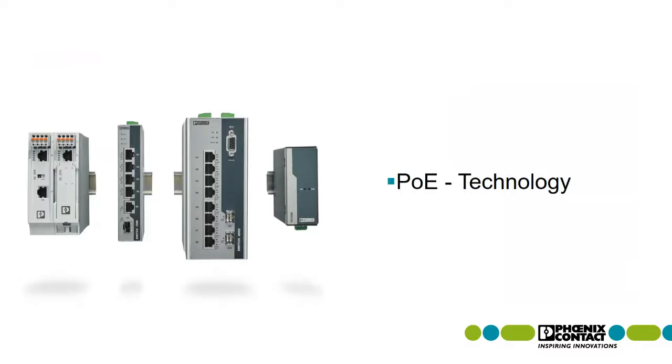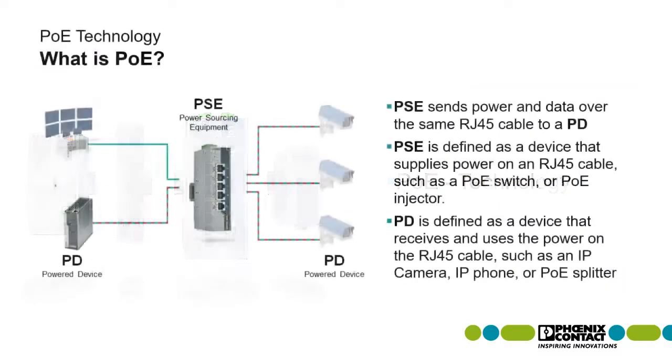So first, taking a brief look at PoE technology. PoE is made up of different device classifications. Mainly, you've got a PSE, or power sourcing equipment, and then you've got PDs, or powered devices. The power sourcing equipment is responsible for sending that power and data to the end device. It's all done over the RJ45 cable in power over Ethernet, and that is how the devices receive their power. The PD, on the other hand, is just defined as the device that receives the power on the other end.